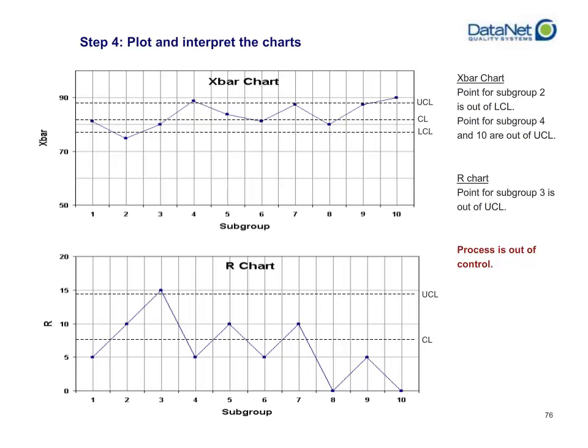However, your X-bar chart is showing you that while that may be the case, the averages of those values themselves are still straddling, or beyond, your upper control limit. Your process itself looks like it's changing and it's out of your historical control. That doesn't necessarily mean it's a bad thing, but it is something you absolutely want to investigate and find an assignable cause for. Because while you are producing a product that has no variation within the individual subgroups, the last subgroup value that you plotted was also equal to your upper specification limit, and that's something that you didn't even plot here.